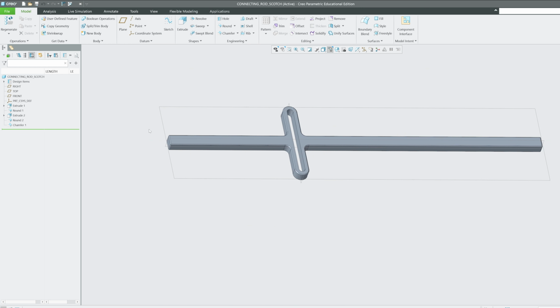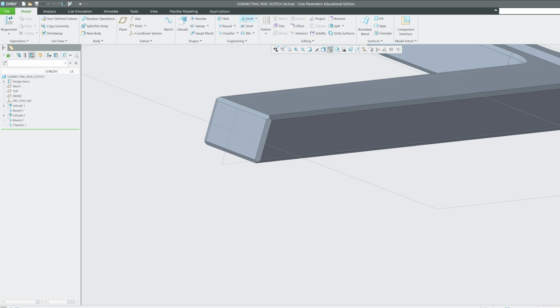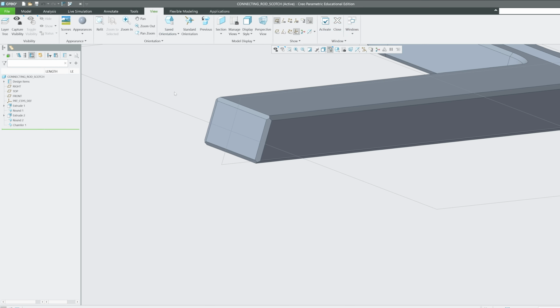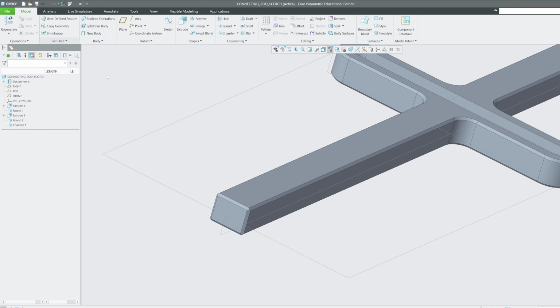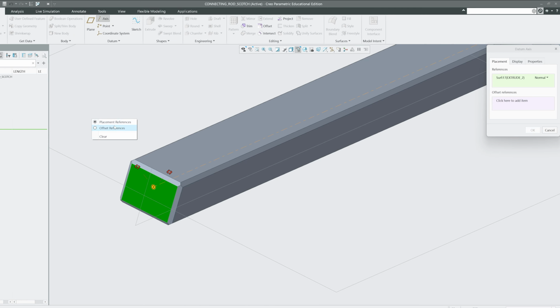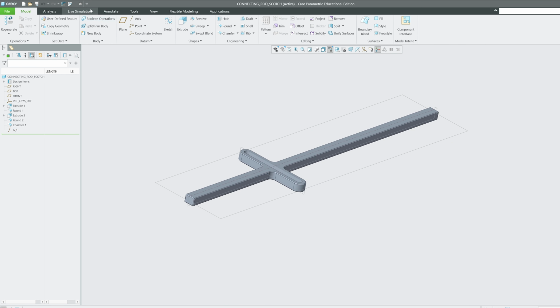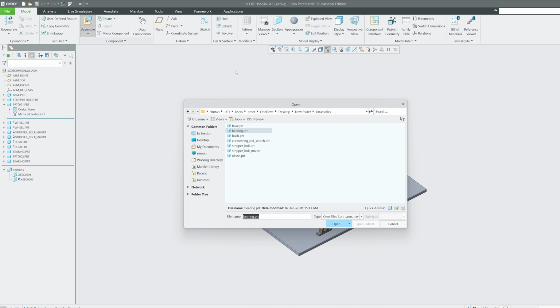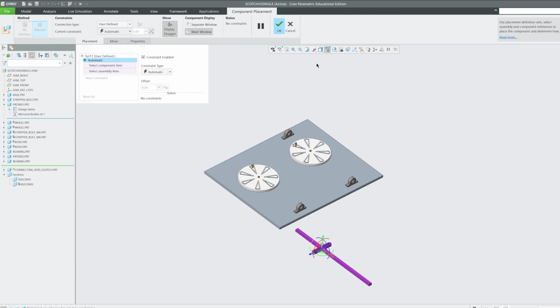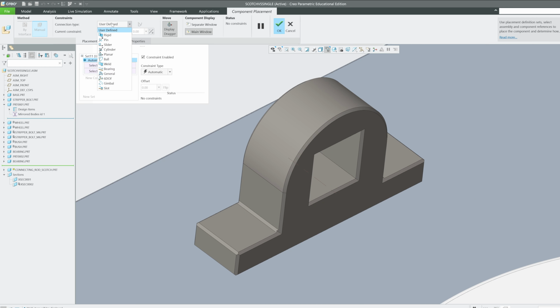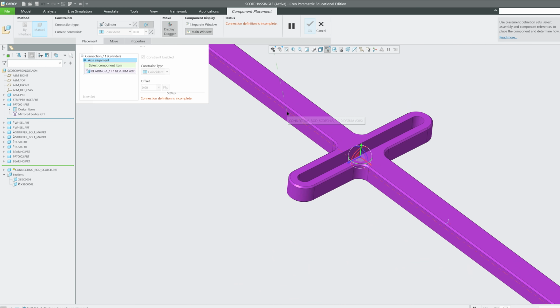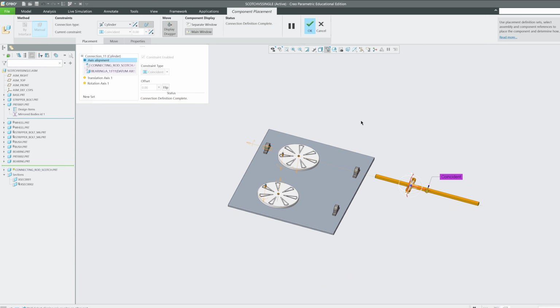All right, so let's also plot an axis here, and let me actually see. Yeah, we can actually rotate it as well. So let me plot an axis. Let's make it 0. This one also is 0. Let's click OK. Yeah. Now let's close this. Now I'm gonna enable this or bring this connecting rod, but let's also enable the axis display. Now here I'm gonna choose cylinder as a joint, and then I'm gonna choose this axis, and then here also this axis. Now this is constrained.